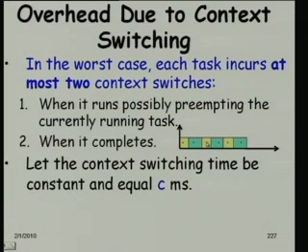So, the higher priority task has undergone 2 context switches, and this had undergone 1 context switch at this point, and after it completes there is 1 more context switch. Just think about it, at most every task incurs 2 context switches. If we develop our expression by that, we will be doing all right, because the higher priority task context switches will be taken care of. They will be added to the lower priority task's completion time.